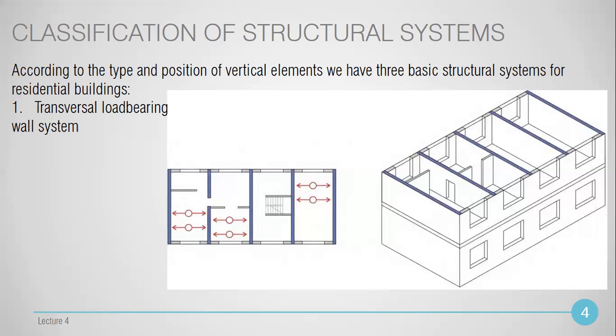So it all again depends on the architectural design solutions, according to the internal processes, for what purpose we design the premises, the rooms, for residential purposes or for offices or administrative buildings and so on. Usually the dimension of the bearing wall, as I told you, is from 20 to 30 centimeters. But 25 is one of the popular ones.